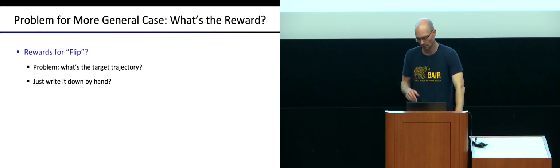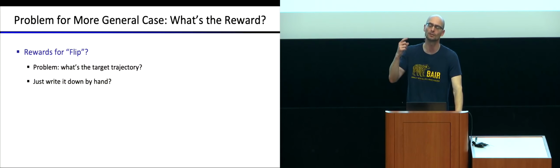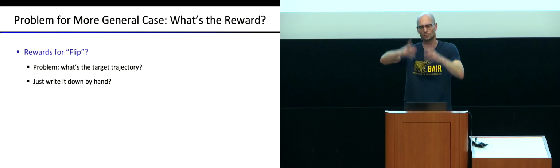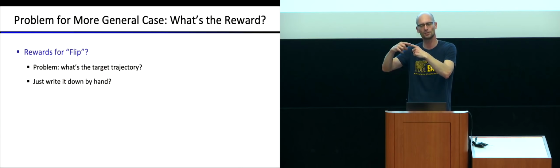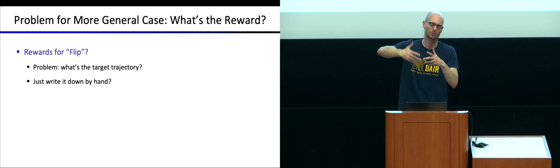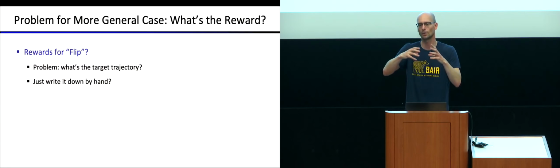Maybe you could say, well, let's write down a reward function by hand, because we get to choose what the helicopter should do. Let's just write down maybe a path the helicopter should follow. You think about, what should the helicopter do when flipping? Well, it should be spinning. But if we just pay attention to spinning, it's going to be dropping, so it should also stay in place. But staying in place is actually not possible, because when you are spinning and you're not able to generate directly vertical thrust, if you generate that vertical thrust in your helicopter frame, you'll move forward or backwards in some way.